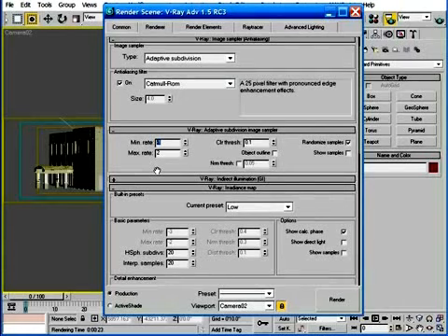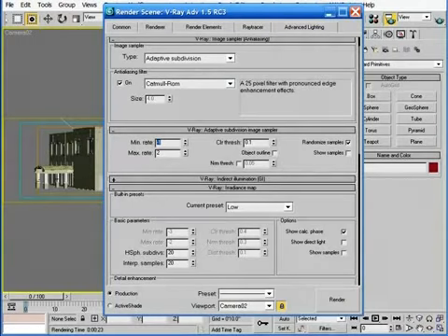And because of this, you really have the ability to reduce render times in a scene. But this particular sampler does not work for all scenes. It really only works in scenes where there are few blurry effects and a minimal amount of highly detailed areas can be found. So in scenes with large areas of smooth surfaces, the sampler really works well. Now I want to end the discussion on image samplers by showing 3 different images and telling you what I would recommend using for each of these 3 different images.